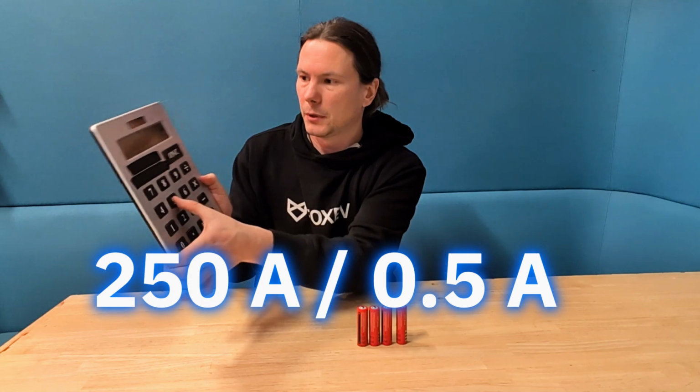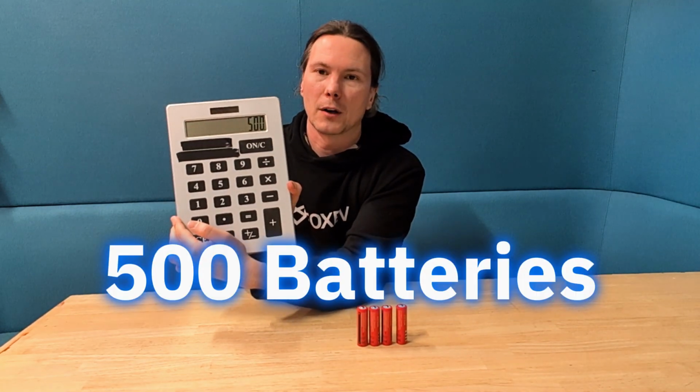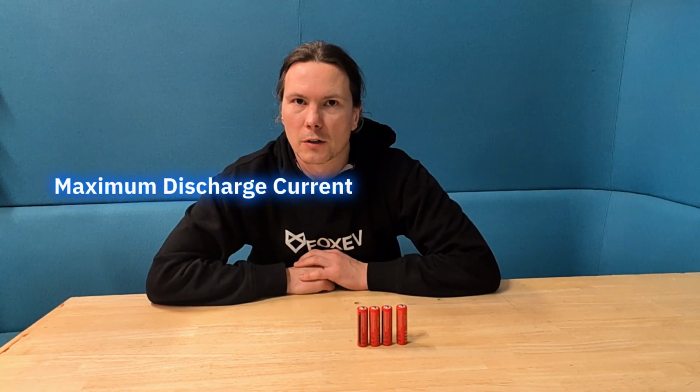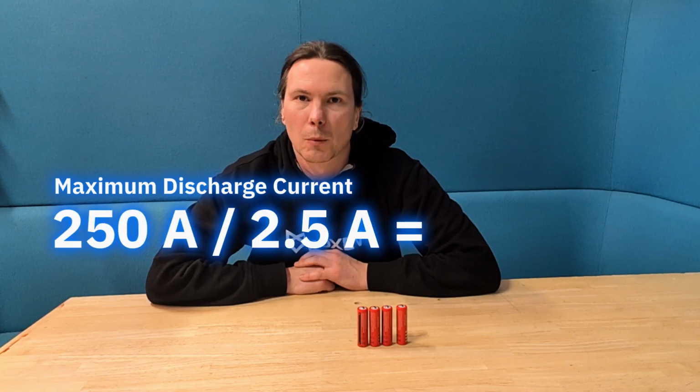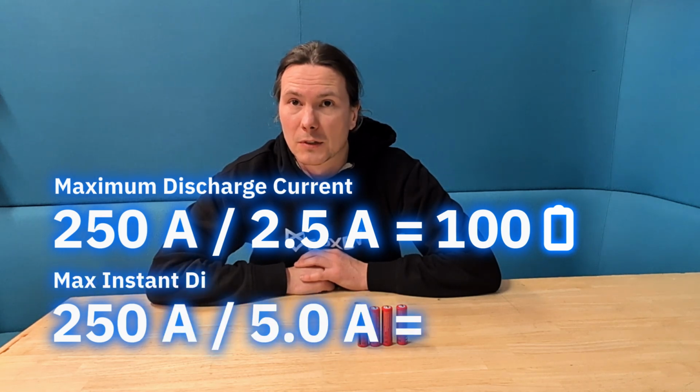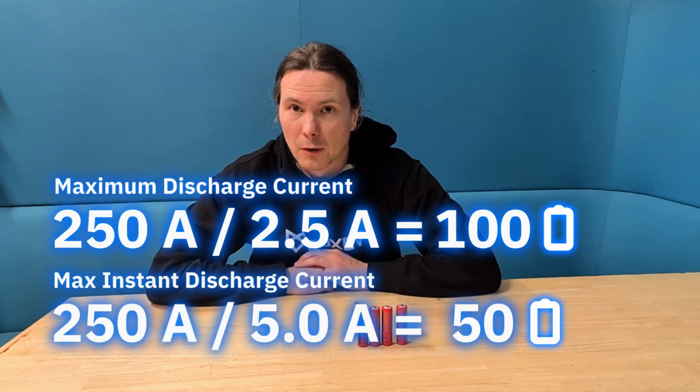So 5 amp is not enough, we need 250, right? To increase the current that we can supply, we need to connect them in parallel. So let's get the calculator out and divide 250 by half an amp. We've got 500 batteries in parallel if we want to use the standard discharge current. In the same way, if we want to use the maximum discharge current, 250 divided by 2.5, that would be 100 batteries in parallel. 250 divided by 5 amp, the maximum instantaneous discharge current, would be 50 batteries in parallel.